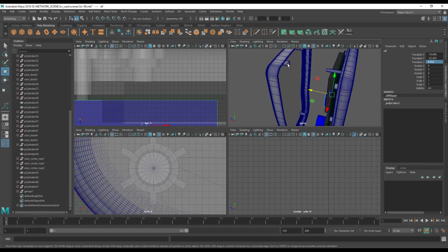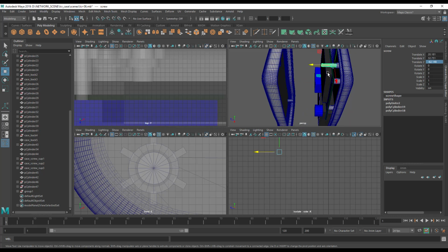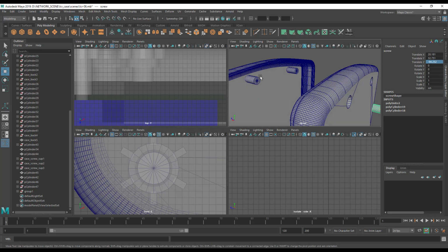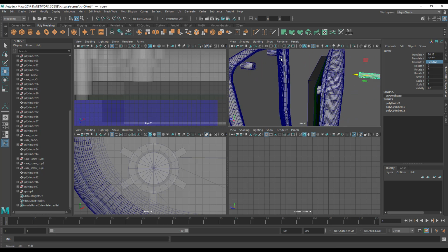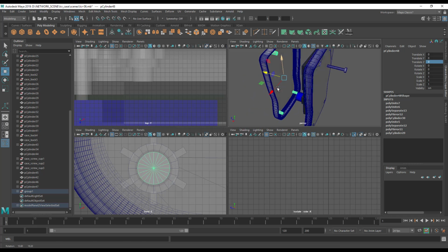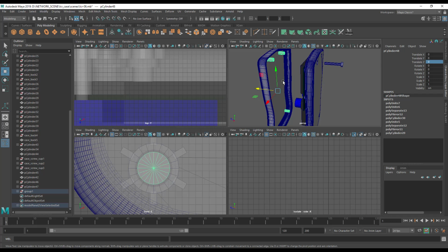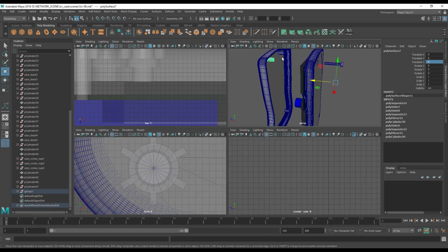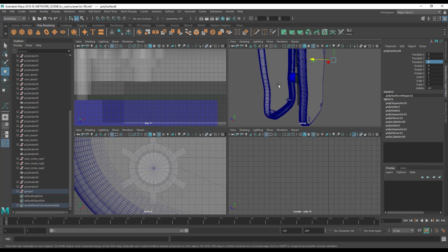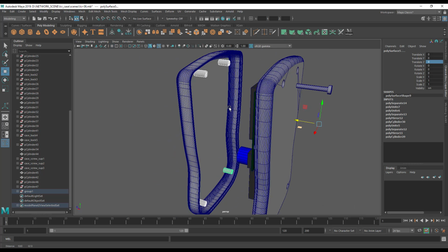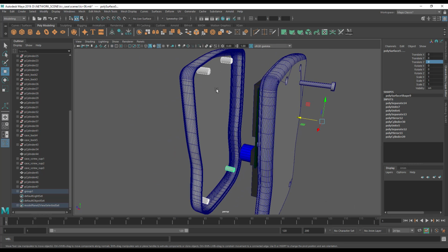So what we need, however, is the holes to receive the screw thread, because this will be solid plastic at the moment, as will this. So this is going to be an easy one. Let's select all these 4. Let us separate these, mesh separate. They should be all now separate objects. They are. Now we can duplicate special, change the diameter, and use them as drills to kind of drill through